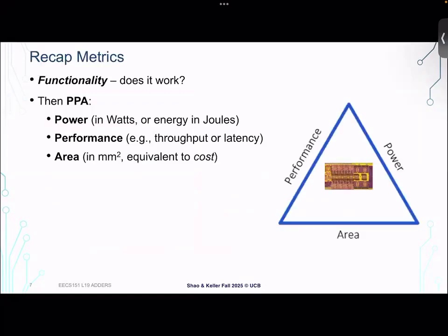We haven't talked about energy or power much yet. So far, first of all, we were focused on functionality, right? And then for the last several lectures, we've been laser focused on delay, on making it fast. We've looked at how to optimize logical effort in order to find the fastest path through inverters or complex gates. We talked about fan out of 4 as this useful metric, rule of thumb for how to size things to optimize the delay. We haven't talked about power or area so much.